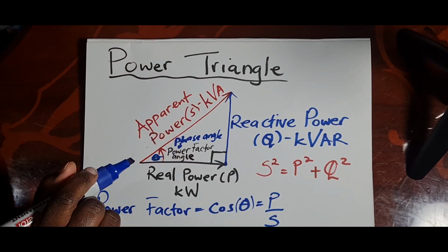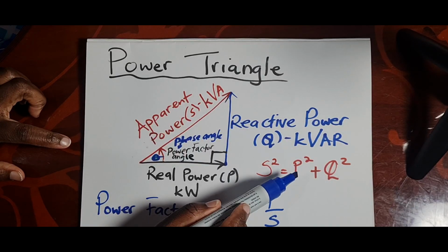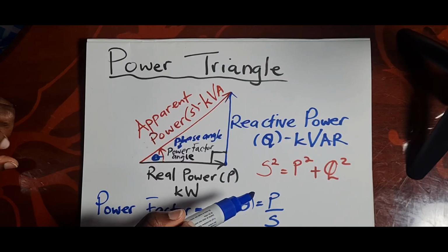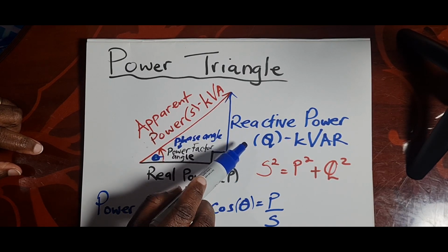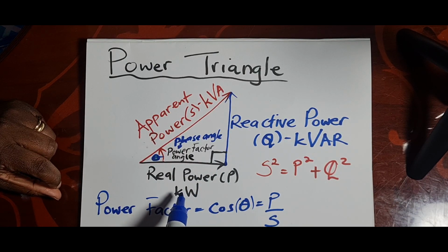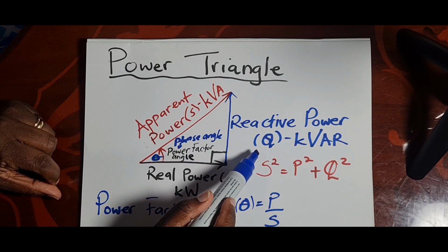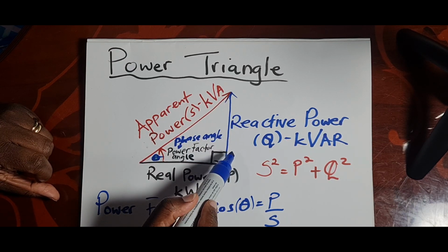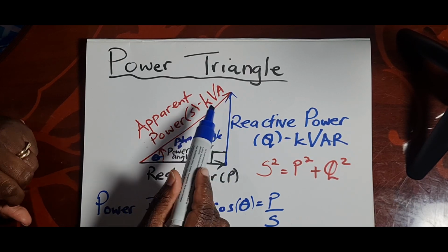Here is the deep explanation of the engineer's shortcut for the power triangle. So S squared is P squared plus Q squared. The alphabetical shortcut: if you forget which letter goes where, look at the alphabet. P comes first, which is the horizontal base, and it's always in watts. It's the foundation. Q comes next. It's the vertical part of the triangle, which is the height, and it's the reactive power, and it's turning up at 90 degrees. S is the result.